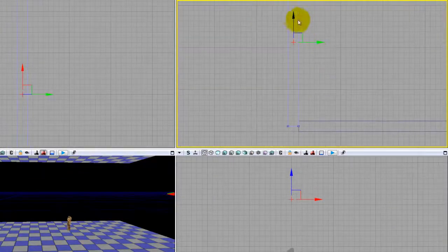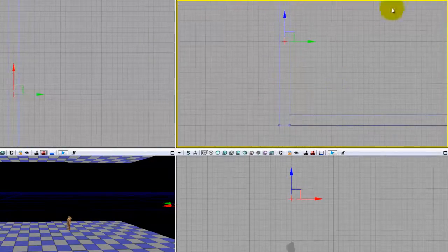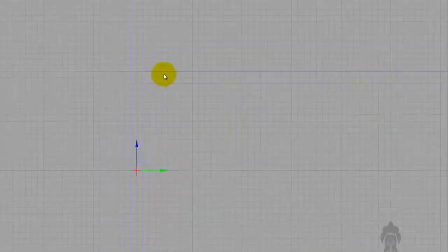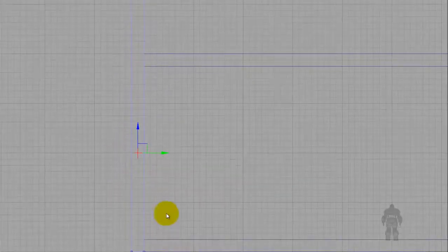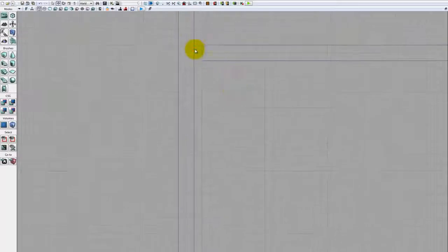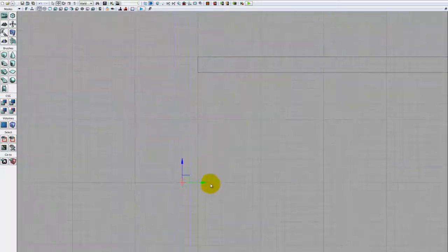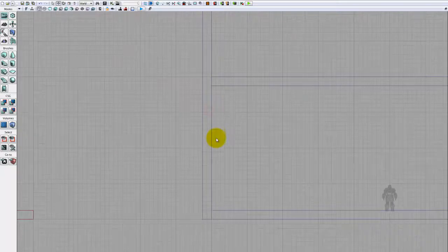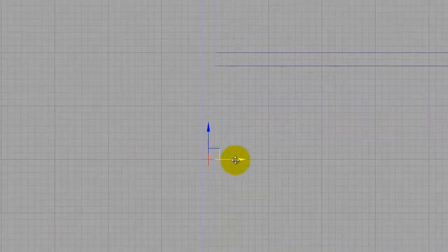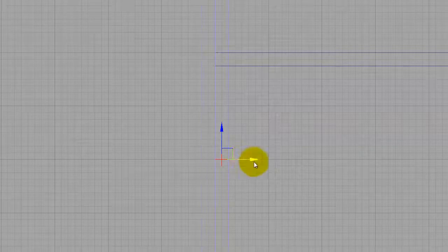And I'm going to drag it down to match. Now this is really important that you need to understand with building with geometry, is you only want your BSP to be right at the borders of each other. So what I mean by that is when I drag this piece to connect the wall, that it just lines up just with the edge. You do not want something like this.